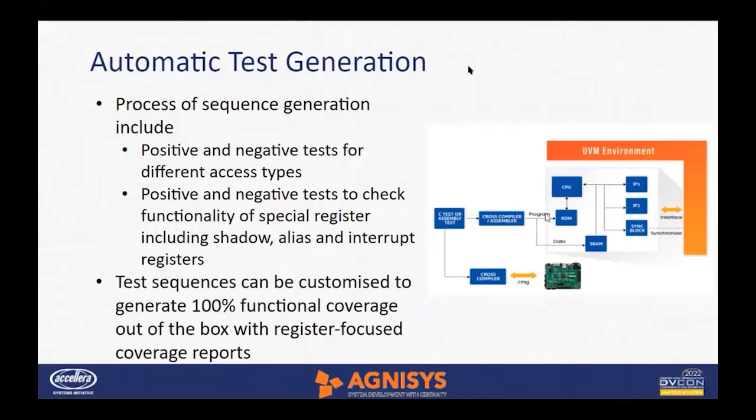So this is the typical diagram that depicts the system level validation environment. You can have a C and UVM mixed environment. If we take a look at the layered view, it has the application software layer at top and the hardware layer at bottom. So we have a UVM environment with the register layer. We have a CPU here where the C tests run and are loaded into the CPU's memory. After that, the CPU generates the bus transaction that writes on the IP level RTL. And we also have a synchronization block that synchronizes the UVM and C environment.